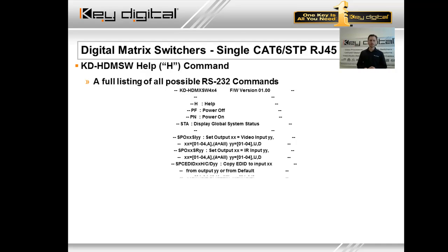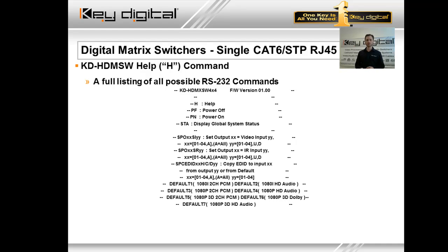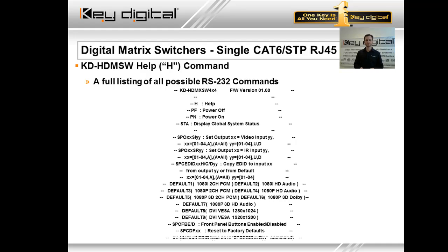The EDID commands, exact same command structure as we discussed earlier. The library is even very similar in the HDMSW 4x4. So whether it be this piece or the step-up models, you know that the software, the EDID handling is exactly the same. Front button enable, disable, or factory default with XX being the value of one of the EDIDs from the libraries there, 01 through 08.